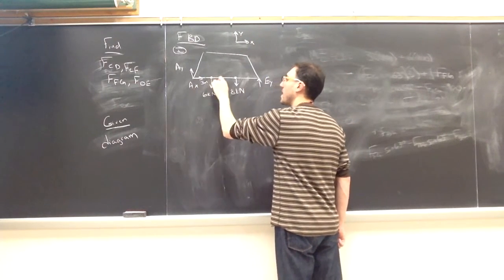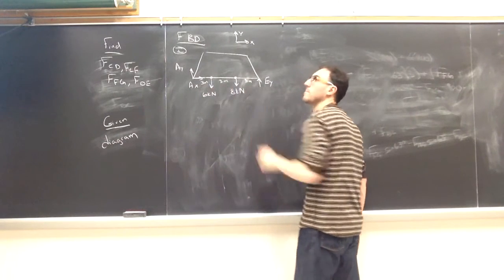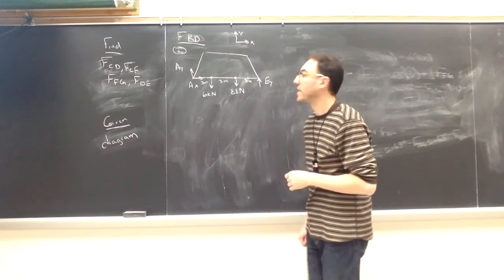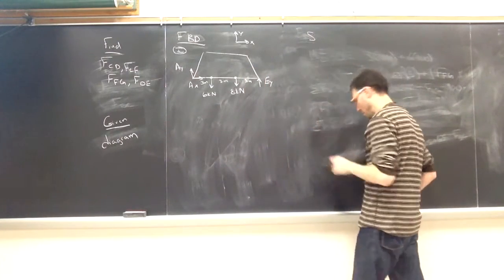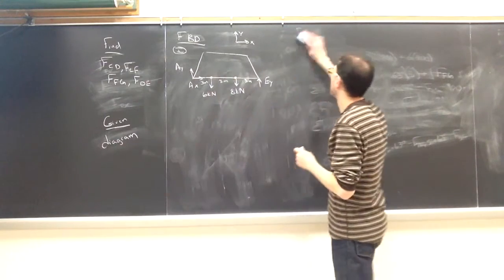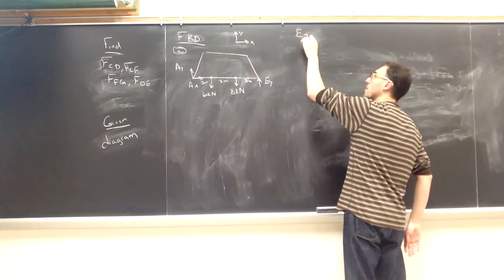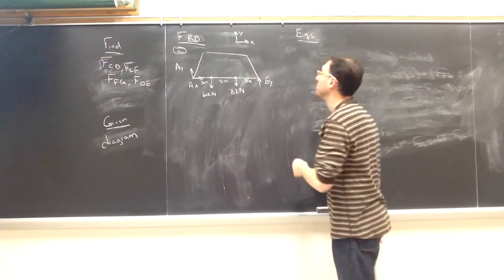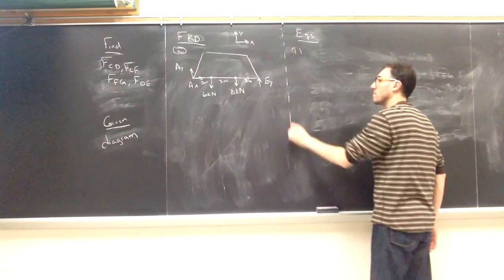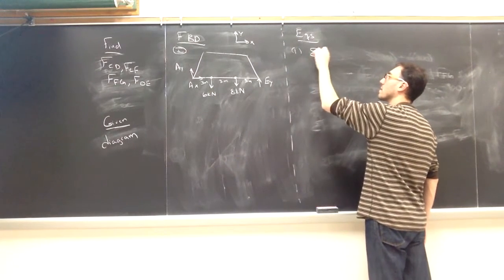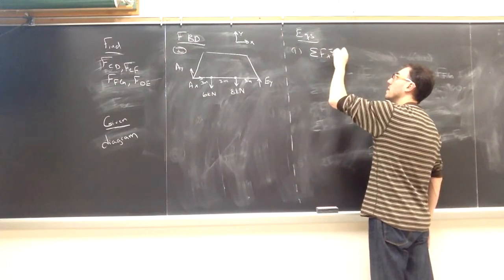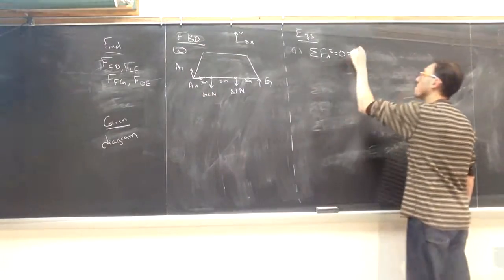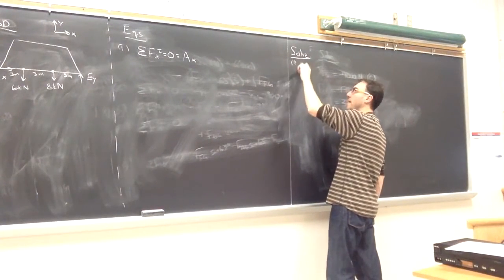And that's 3 and 3 and 3. Those are the only forces acting on this, so I can use this to write my equilibrium equations in order to find these external support reactions. I'll start with the x direction. I just have AX, so that makes things simple. AX must be 0.